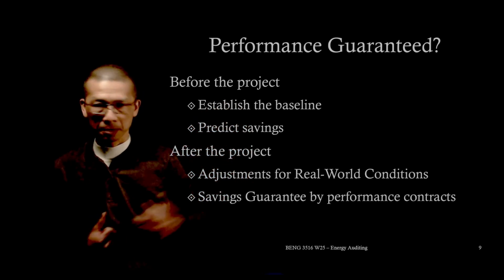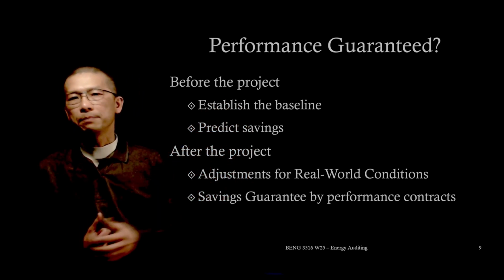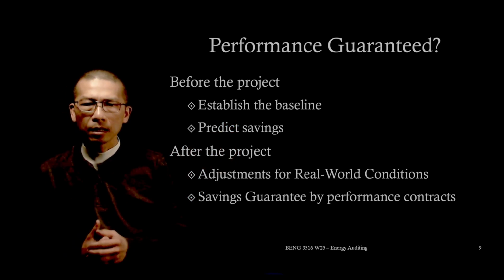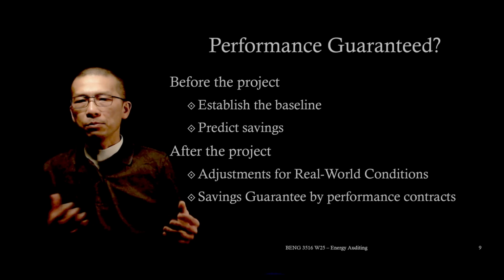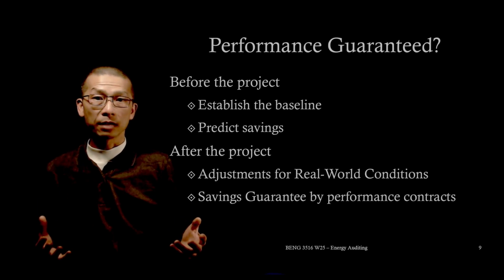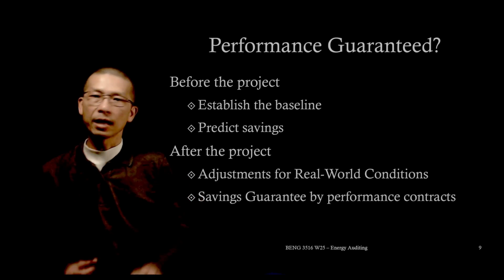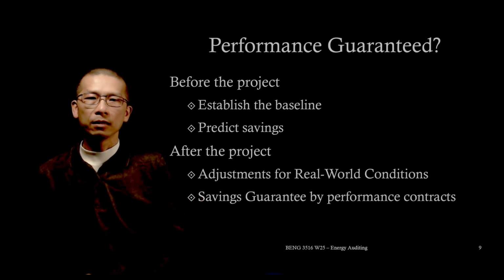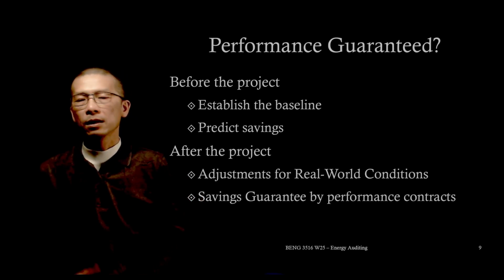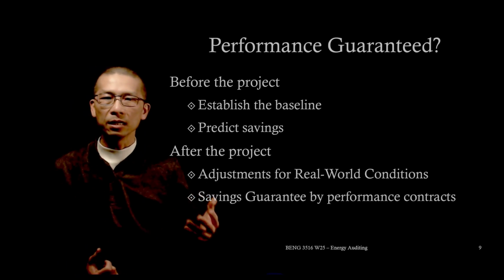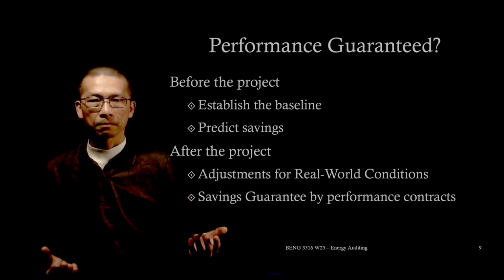First, establishing the baseline before the project. Before implementing energy saving measures, MMV professionals will measure and analyze the current energy use. That can include historical energy data like utility bills and interval meter data.